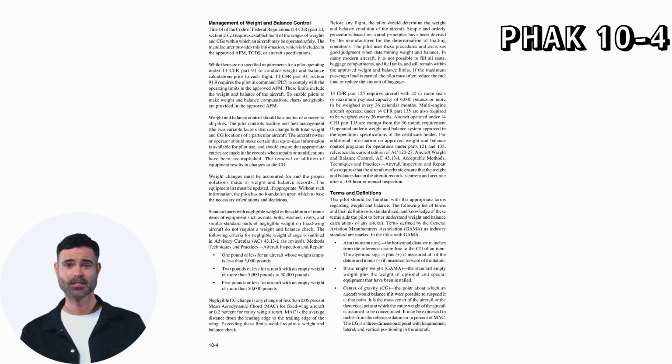While there are no specified requirements for a pilot operating under 14 CFR, Part 91 to conduct weight and balance calculations prior to each flight, 14 CFR Part 91, Section 91.9 requires the pilot in command (PIC) to comply with the operating limits in the approved AFM. These limits include the weight and balance of the aircraft.